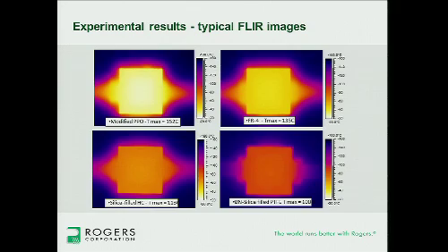This is the prettiest part of doing any kind of thermal simulations. These are all on the same temperature range for colors. You can see that we're getting a 152 degrees C temperature rise on the modified PPO, about 135 on the FR4. The silica filler in the 4350 brings it down to 113, and the boron nitride filled material brings it down an additional, substantial amount to about 100.